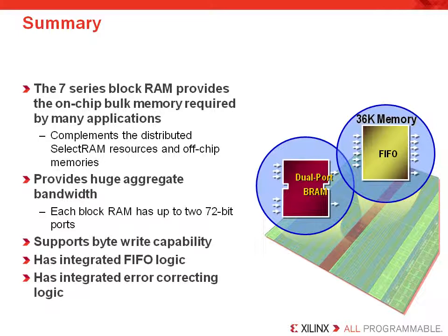It also has the ability to support byte-wide capabilities, has an integrated FIFO logic that's also dedicated in the hardware, so that you waste no extra logic by converting your memory into a FIFO. It also has your integrated error-correcting logic that's dedicated to silicon as well. All in all, it's a lot of features, very good performance, a terrific resource.